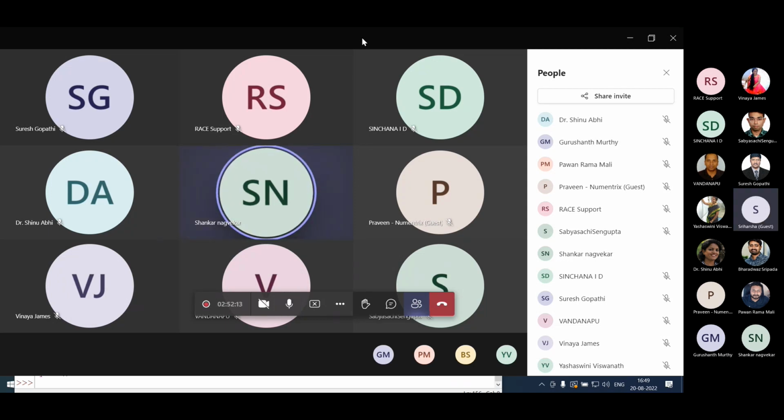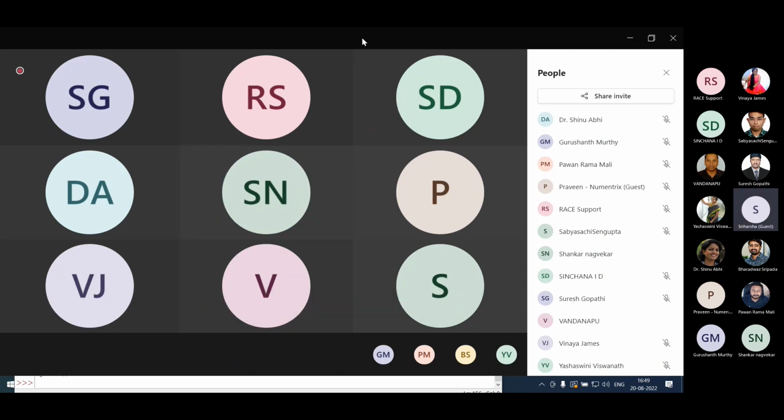Actually, I am planning to put together one application with visual detection, that is, recognizing the object name. It includes a Raspberry Pi and a camera. In the Raspberry Pi, we have a Python shell, and in it we import OpenCV. Using OpenCV, we communicate with the camera, and the camera reads the image. In the background, we have a dictionary of data, in some XML form, and this dictionary of data will be compared with the real image from the camera, and when matched, it will identify the location in the image where the buffalo is.